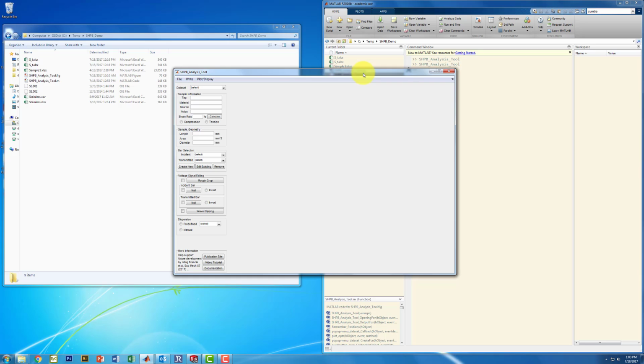First, how do you get your information in? So, importing data. Try to anticipate as many different ways you could import data in. Go to File, Load, Gauge Voltages. Your incident and your transmitted bar could be grouped or not grouped. If they're grouped, you could have them grouped in an Excel file together, like two columns right beside each other.